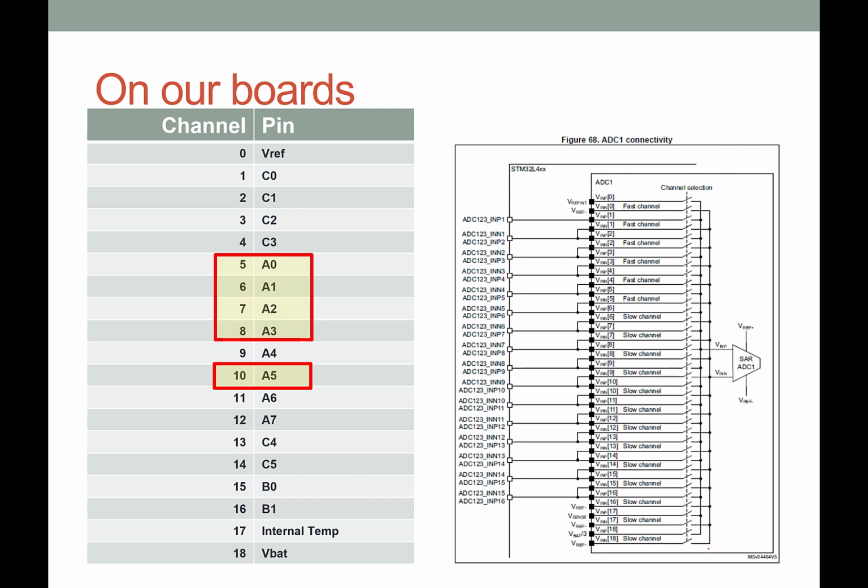We have easy access. Here it shows us where the channels are. They're tied to GPIO port C0 for the first channel, C1 for the second channel. Now, all these are on the first analog to digital converter, but ADC1 has 16 channels that we have access to.